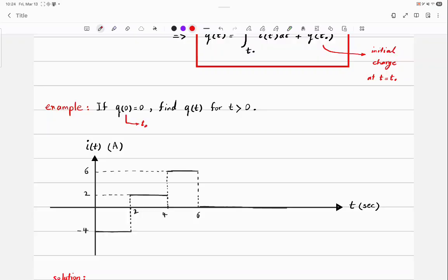Perfect. Do you agree that the current is entering the negative terminal? So, this is my question. If I multiply 2 by 2, what kind of power do I find? Supply power. So, what do you do to that to make it absorb? Add a negative sign. That's it. Negative 4 watts.